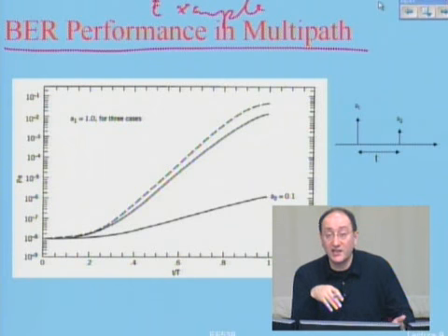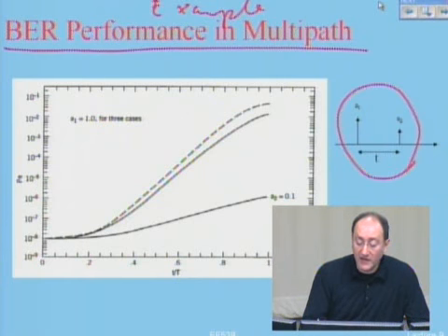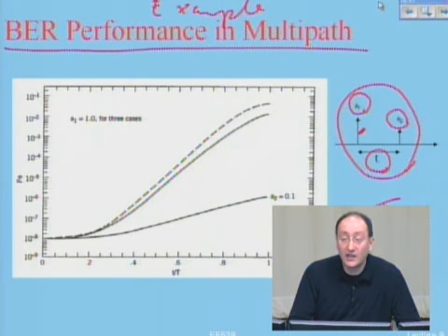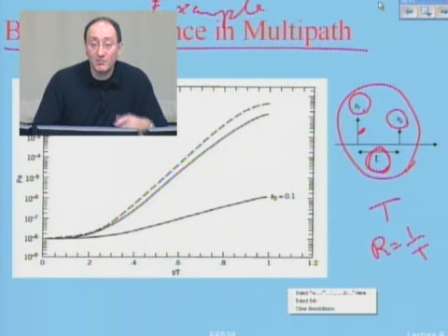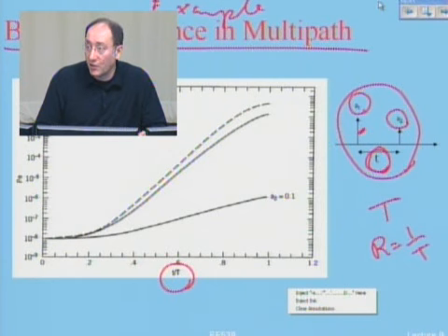If I want to calculate it now, it is a little bit complicated. So I take two paths, a channel with two paths. Path 1 has magnitude A1, path 2 has magnitude A2. The distance between the two paths is T, and my pulse duration is capital T. And I have raised cosine pulses. So my data rate is what? 1 over T. Okay? Now, T is my maximum multipath spread. Okay? Small T over capital T is the normalized spread of the pulse. Do you follow that?